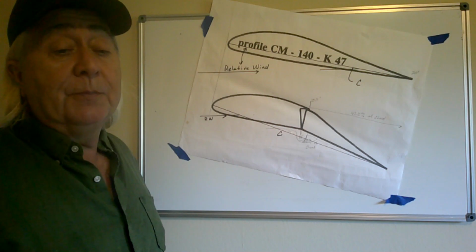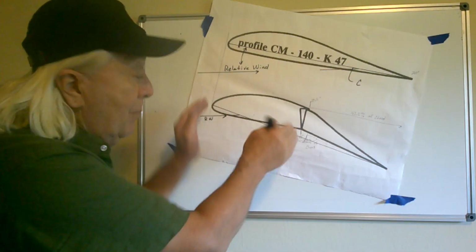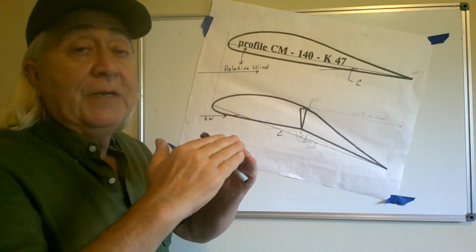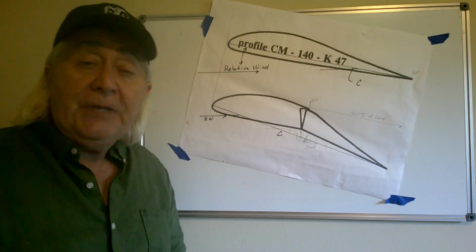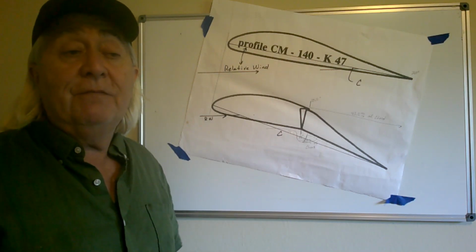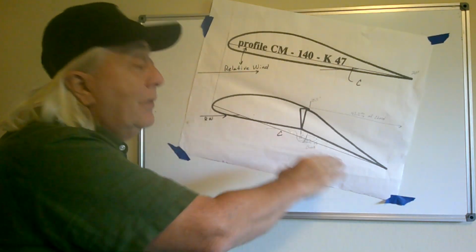Hard to believe. I deployed the flap and I stalled my aircraft because you're essentially morphing the wing. It's one thing to put down a little flap back here. It's another thing to bend the airfoil in half. You're completely changing the design of the aircraft in flight. By the flick of a lever, you now have a highly cambered airfoil that's at a totally new angle of attack.